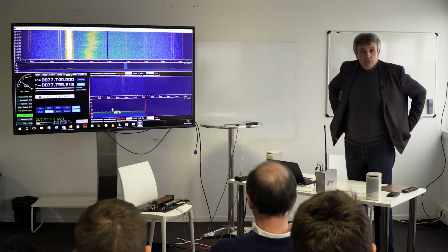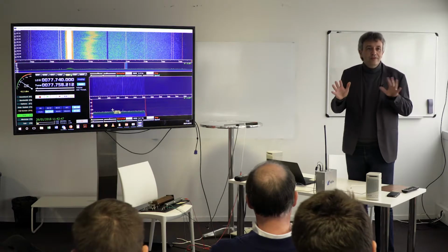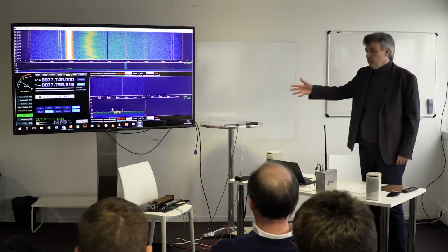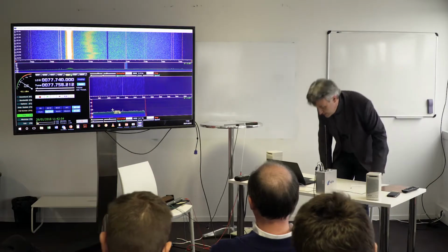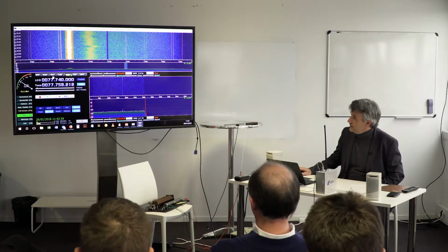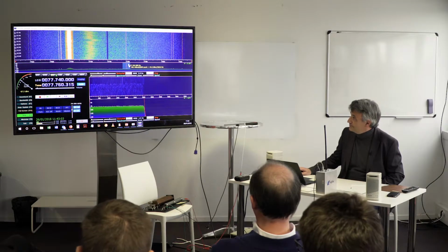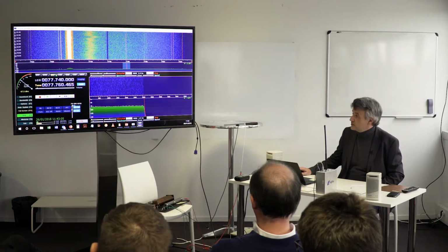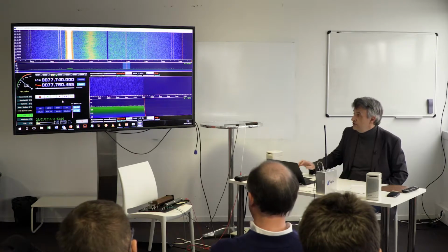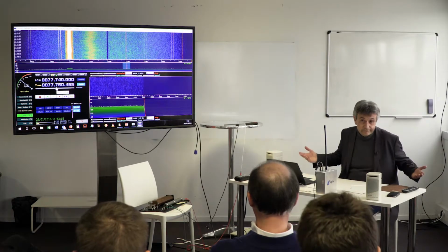Okay, and you try to be as static as possible. Try not moving too much around the transmitter. So you see, we receive the signal. We can say that we see the signal. It's not a strong signal. So once again, if I'm going back to FM, for instance, I still have a lot of noise in my reception. So a small FM walkie-talkie would not be able to exploit this signal. No way. Okay?